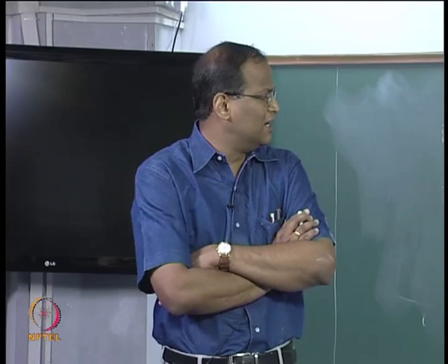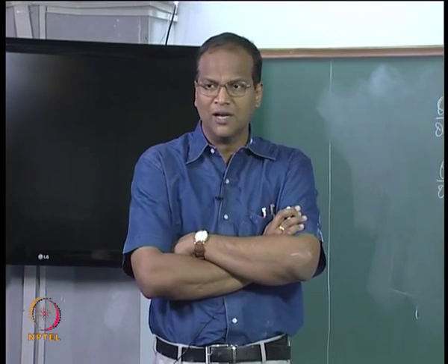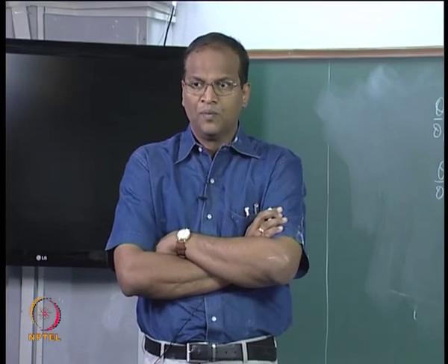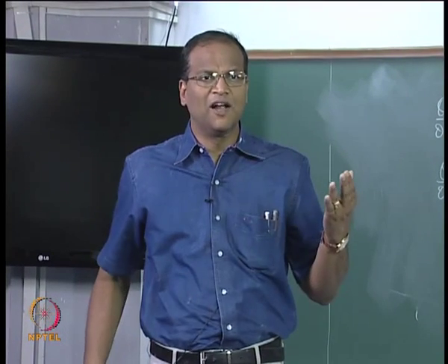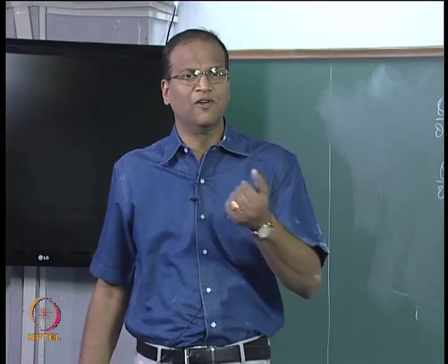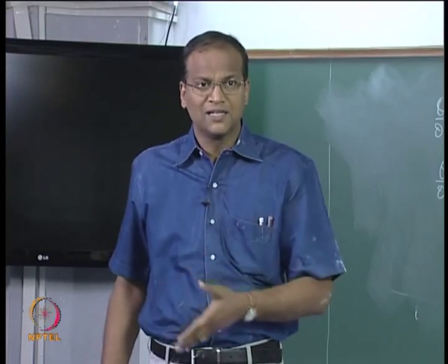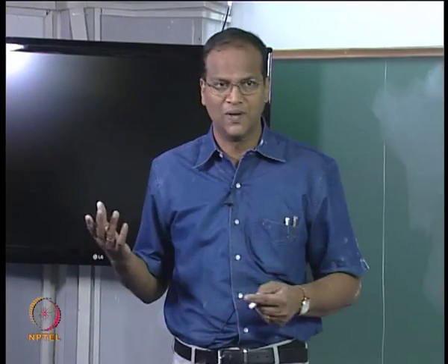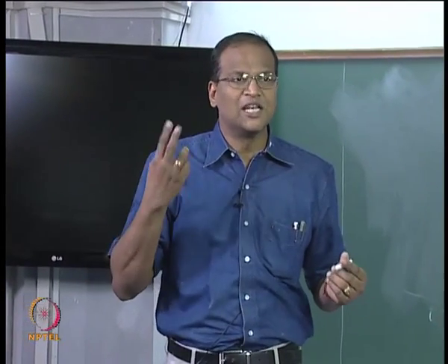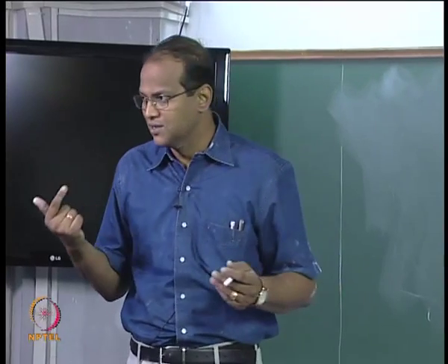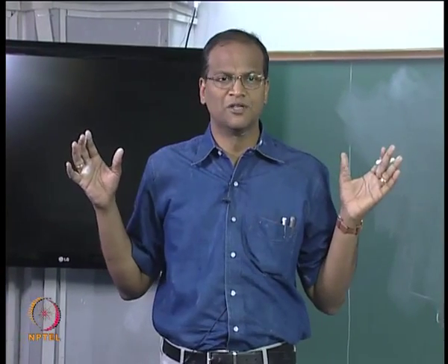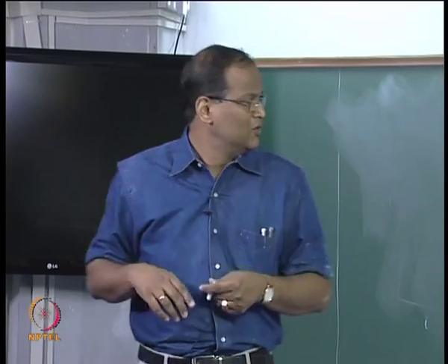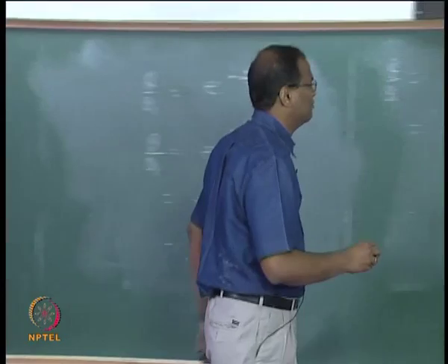Now I take d theta by dt, d theta by dx, d square theta by dx squared, and then I will arrive at terms on the left side and right side. Left side will be a function only of time, right side will be a function only of x. If both have to be equal, both of them have to be individually equal to some constant, I call it lambda square. Then I am essentially breaking down the PDE into two ODEs. I solve these, this is called the superposition principle. I combine the solutions and using the boundary conditions I get A, B, C, D. What you are essentially doing is called the method of separation of variables.